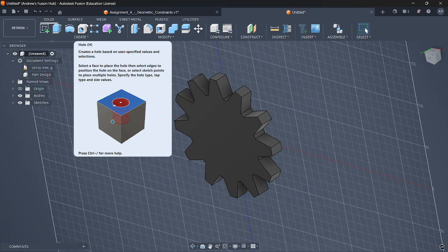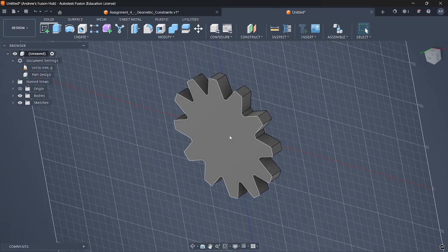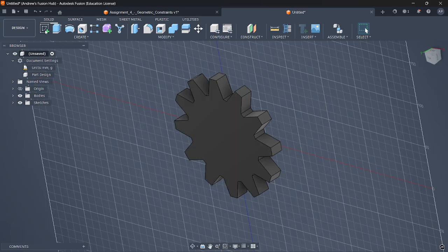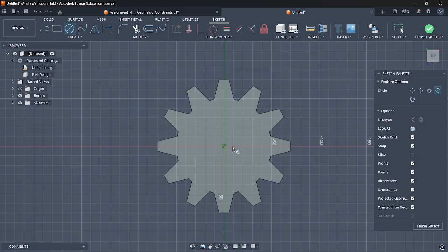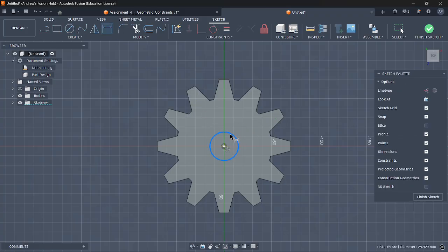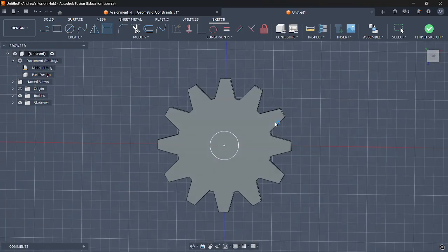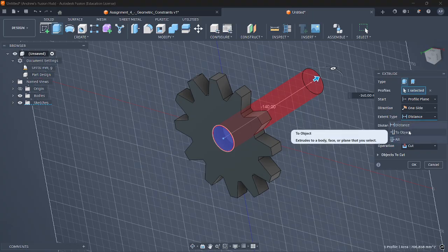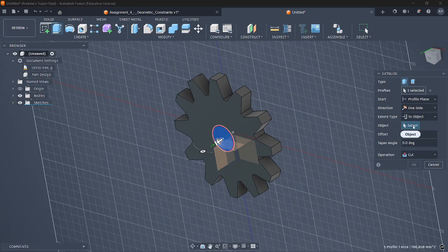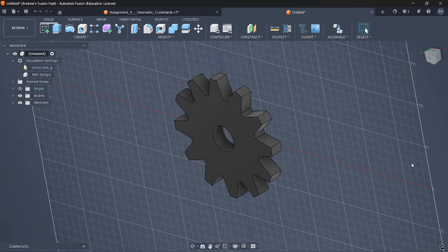When I'm CADing by myself, sometimes it's kind of bad practice, I'll just ignore the hole tool and make an extruded hole, right? Especially for something that doesn't have threads in it. It's sometimes a lot faster to just sketch here, I want a circle here, add some dimension, like 30, and then extrude it and call it a day, right? Like that was fast. Oops. Well, now it's less fast. But this was pretty quick, right?